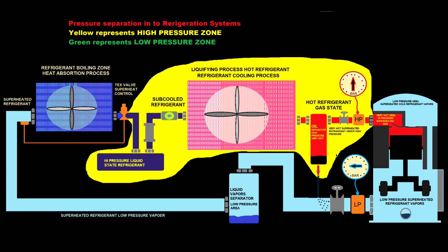When you go over the thermostatic expansion valve onto the evaporator until the compressor suction, there is the lower side. So what does the refrigerant do? The refrigerant absorbs heat through the evaporator and it dumps that heat to the condenser.